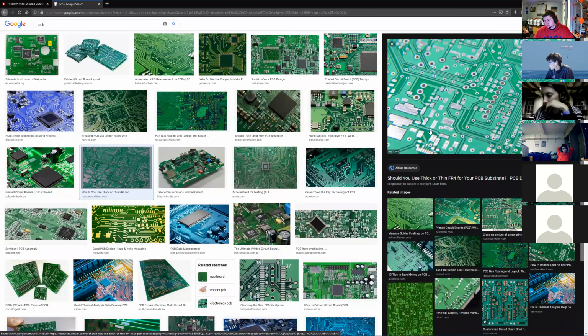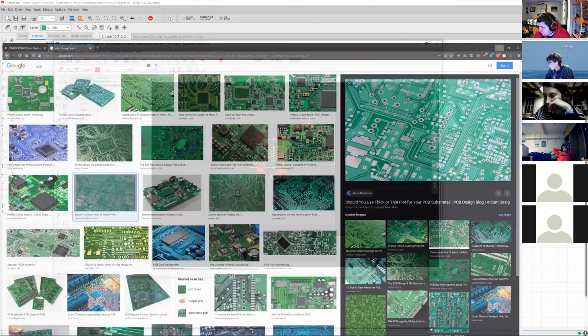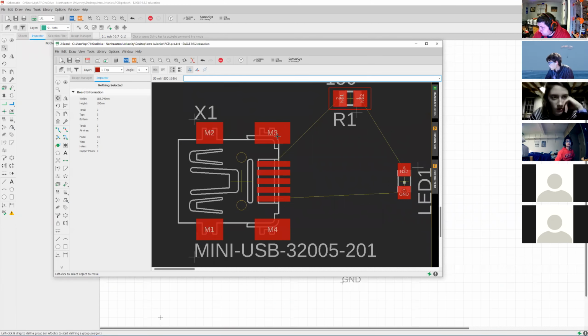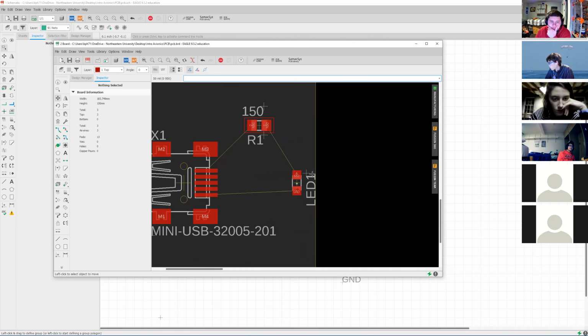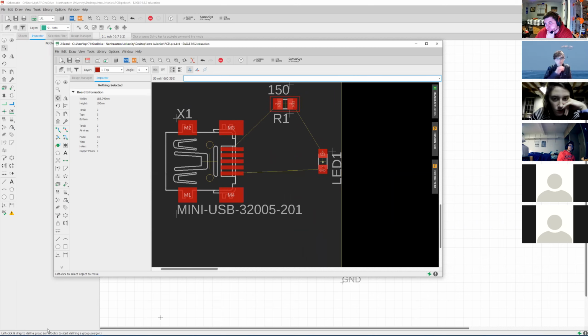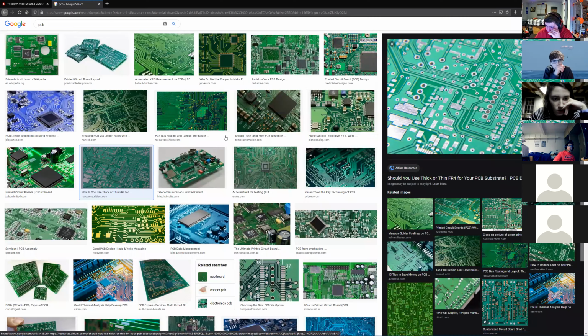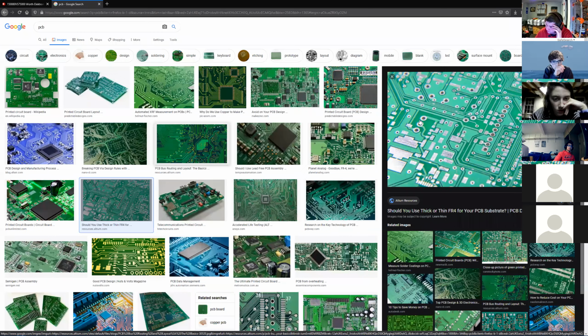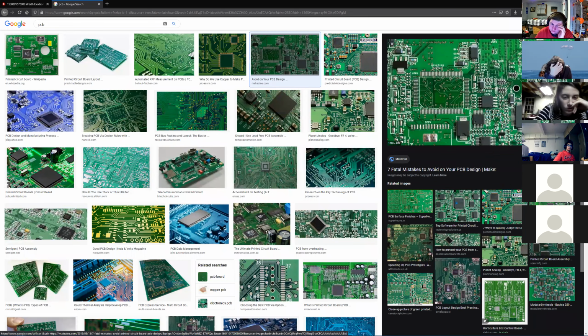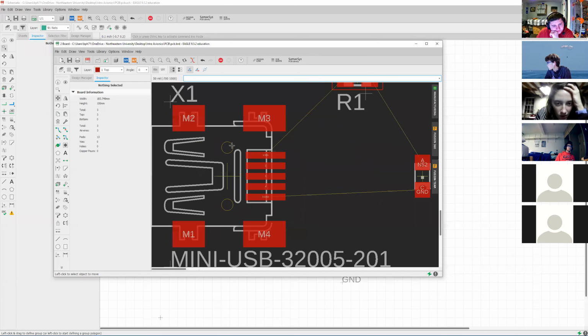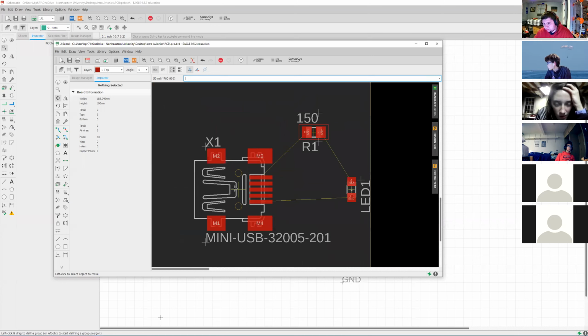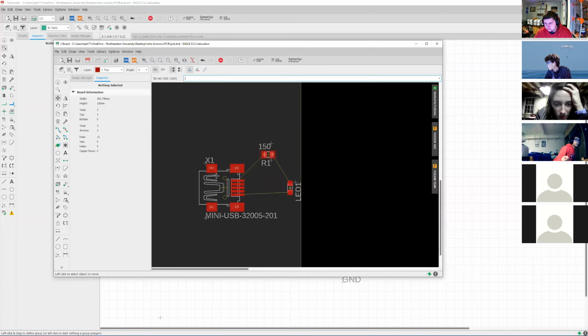They've coated them with tin or something like that, but all of that exposed silver you're seeing is the same as this red that you're seeing here. So those are sections of exposed copper. Now, anything in white is something that your manufacturer is going to print on your board in silkscreen. So all of this text that you see here, that's what you're seeing in the white. The other layers, or the other colors you see here, probably won't show up on the board.